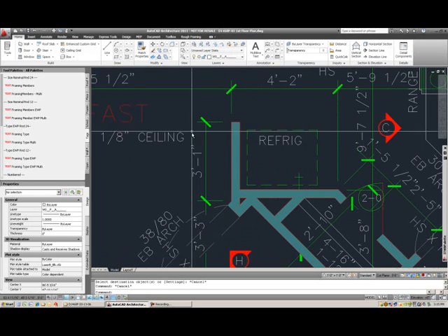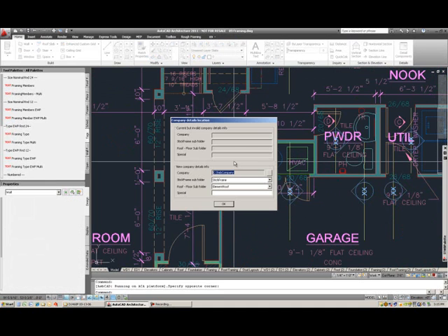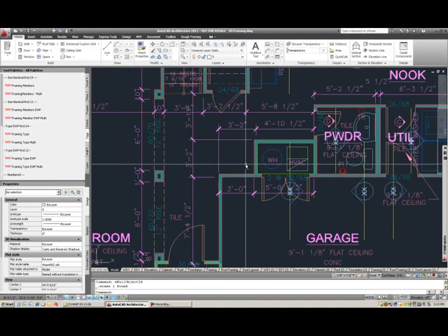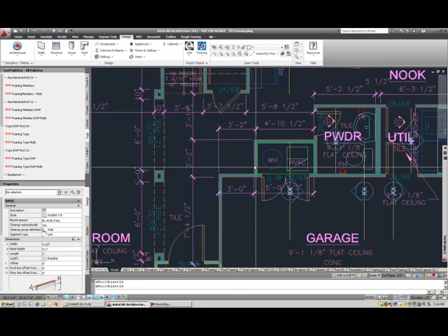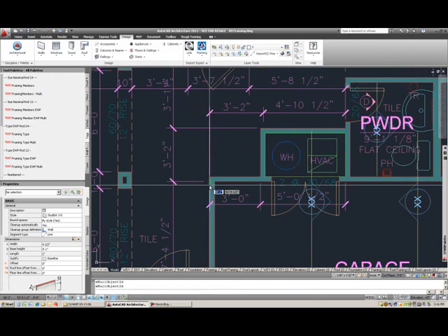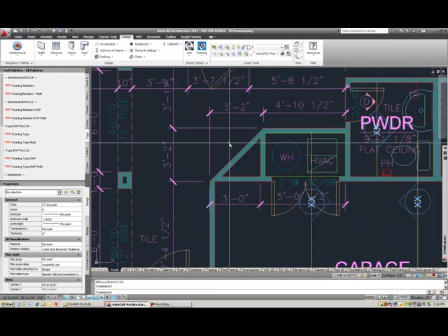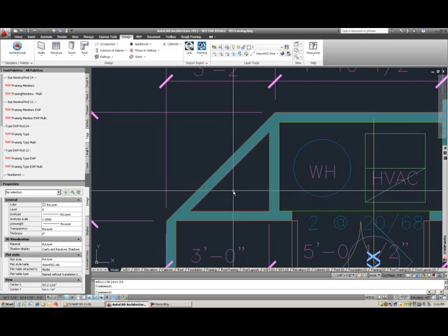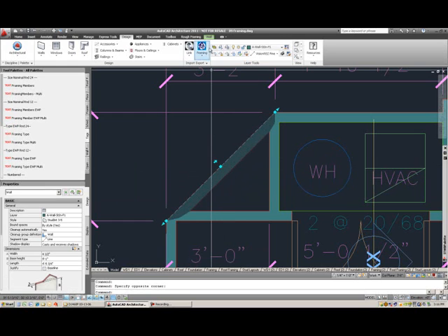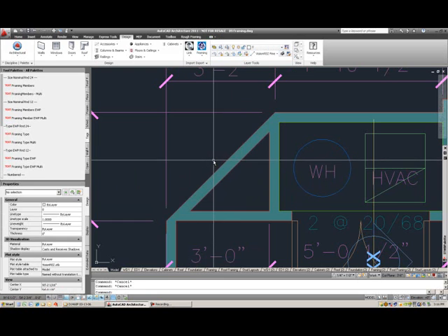In a modeling process, say I delete this wall here and actually want to draw that wall. I'll get into a view of actually modeling. What I would do here is select the wall that I want to draw, and then I just draw from one point to another. When I draw, it cleans up, it puts the line where it needs to, puts the hatch where it needs to, and I didn't even have to consider what layer anything was on because this was automatically generated. This is the layer, and it was automatically generated from what we call a layer key.